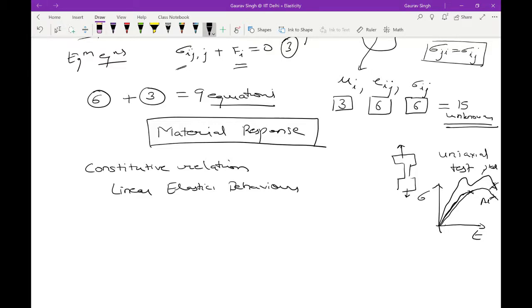So what you would observe is that a ductile material like aluminum or steel has a very large strain before it actually fractures. But a brittle material like chalk, rock, cast iron and so on, they will fracture only after a very small strain. Okay, so the ductility, which is measured as the length of failure minus the initial length, is very large for ductile materials and very small for brittle materials.